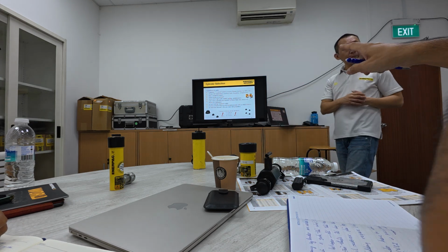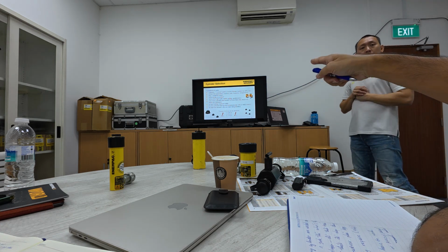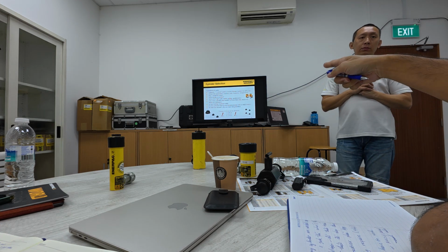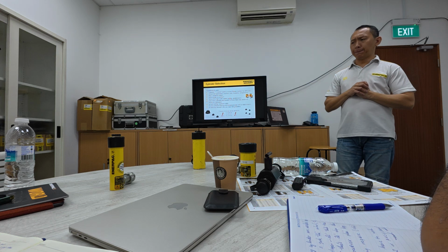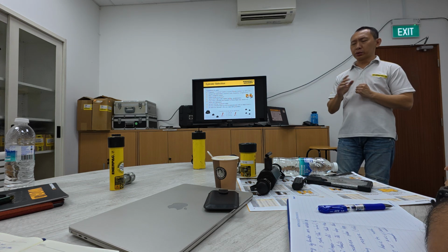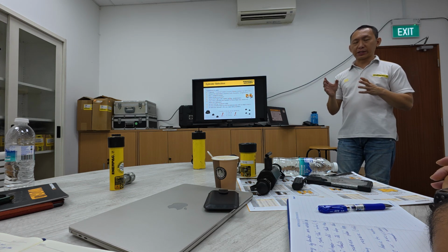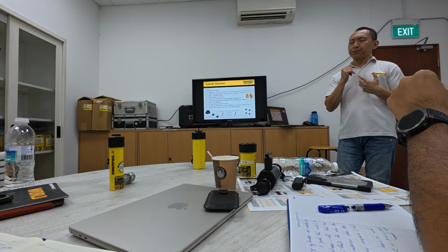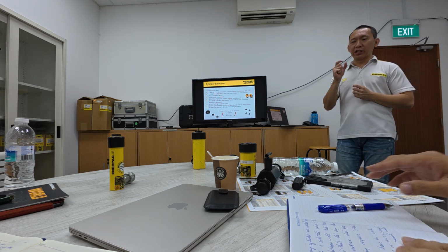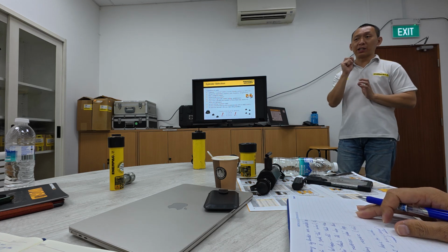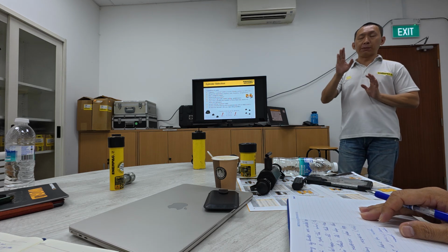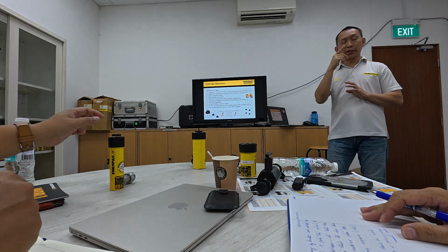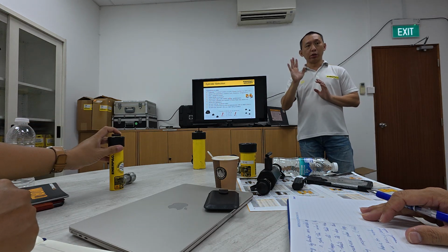Excuse me, do we have any kinds of cylinder to use with side load? Most cylinders have a certain side load capacity, so they can take certain levels. It's not that they totally cannot. There are some cylinders that cannot take side load, for example the lock nut cylinders, because it's threaded. That type cannot take side load, zero.